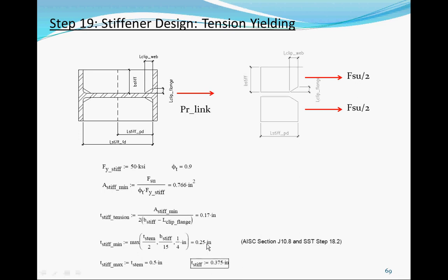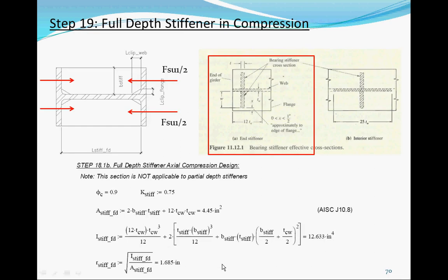So choose somewhere between the minimum and maximum. I just say, well, since we use a shear tap, all the plates are 3/8, I'm going to keep all the plates the same thickness. So when they order it, you could just cut it from the same thickness plate. So I just say order 3/8 inch thick plate. Okay, so that's the one-sided one.